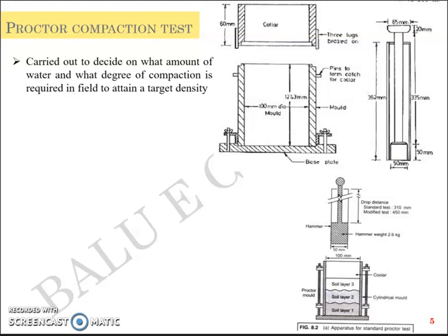For instance, if the site engineer specifies that the density that he prefers is 1.8 gram per cc at site, you'll be asked to carry the soil to the laboratory, test it, and give back data which would tell you the water content which will give 1.8 gram per cc. Just an example, right? Now this test provides the relation between the water content and the dry density.